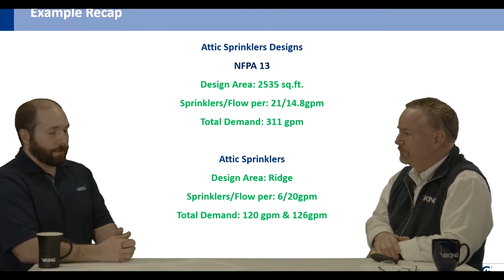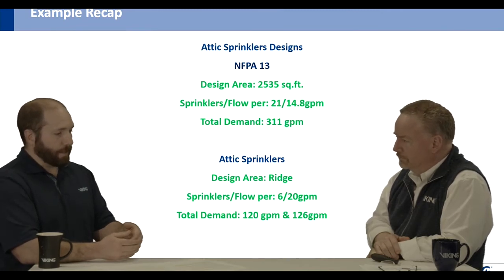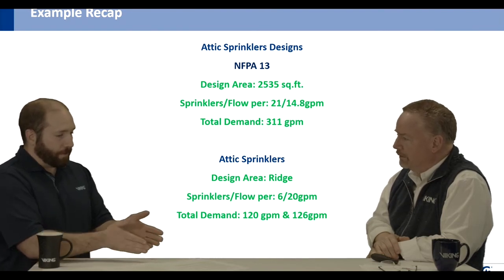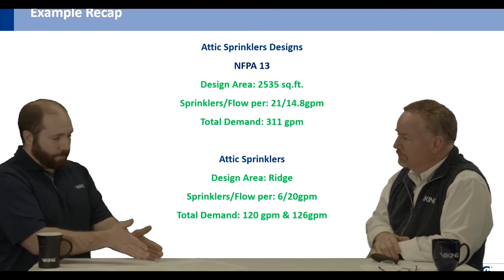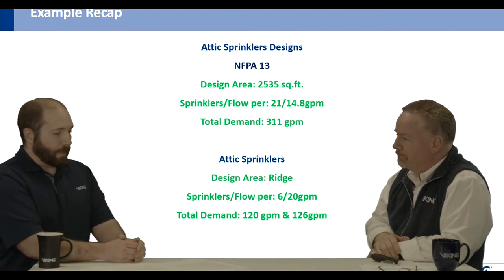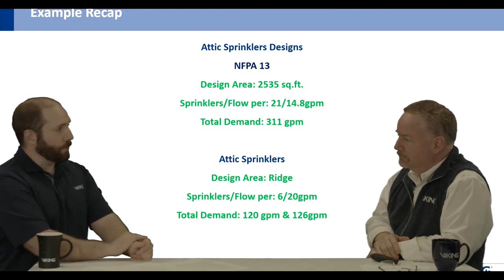The answer to that question is no, you can't. They aren't specifically listed to be used by themselves. They are a sprinkler that's listed in combination with our other sprinklers. So you could do a low flow design if you're using BK 697s, then you would have the VEP. Otherwise, it's the back-to-back, the single directional and the hip in combination with the attic upright.